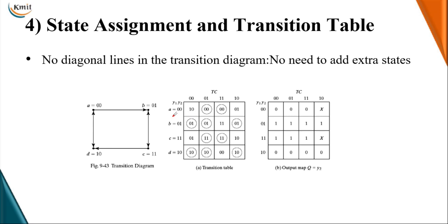State transition, using your toggle flip-flop, here present state is 0, next state of your capital Y1 is 1. So 0 1 is the set state which denotes here. So the SR flip-flop, we have to draw this with the SR flip-flop. So the SR flip-flop excitation table is small y1 and capital Y1. If I take 0 0, your SR inputs are 0 don't care. So 0 1 is 1 0, 1 0 is 0 1, and 1 1 is don't care 0.